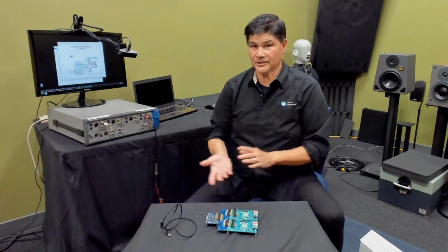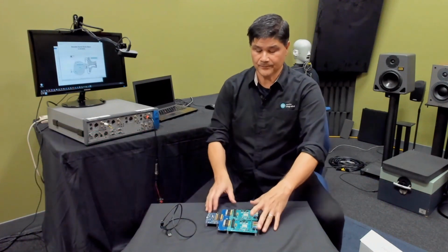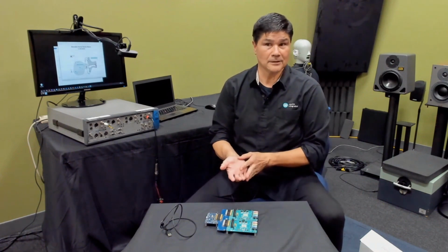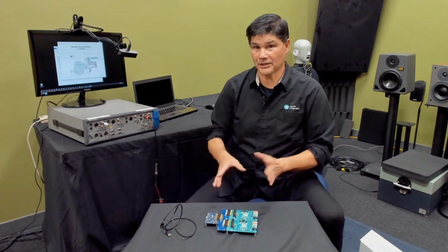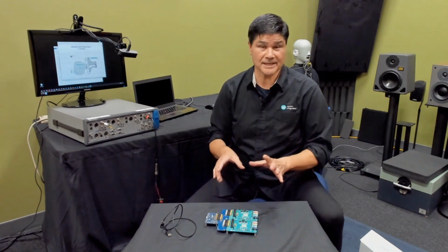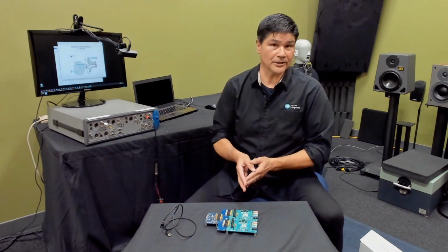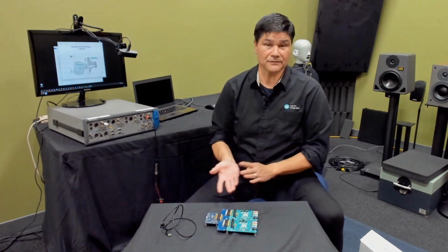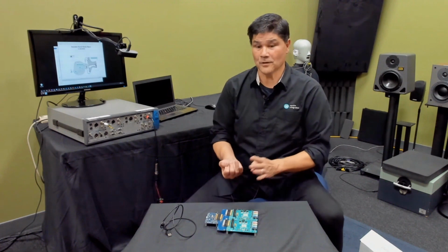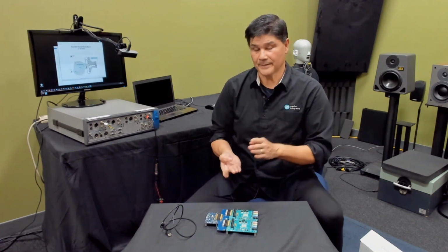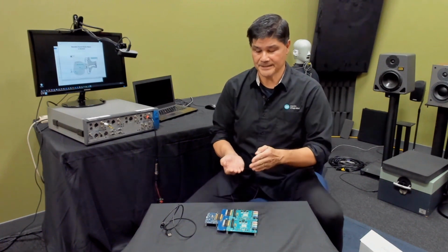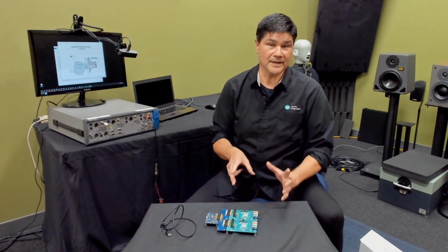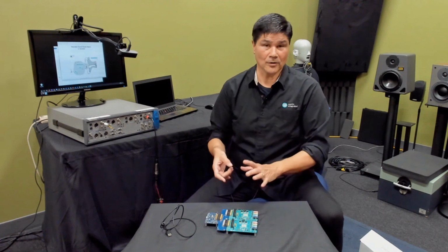Let's go ahead and start looking at the GUIs. There are 2 GUI options for this system. There's the Max98050 evaluation GUI, which is the general GUI that gives you access to all registers inside the part. And there's another GUI called Hearable Sound Studio Basic, which gives you access to all the digital filter tuning. That's for digital filter 1, digital filter 2, the playback compensation filter, as well as the DRC filter and also EQ filters. With the Hearable Sound Studio Basic, you can also do hardware-based evaluation.